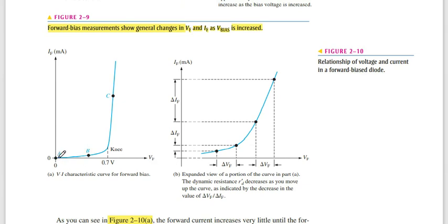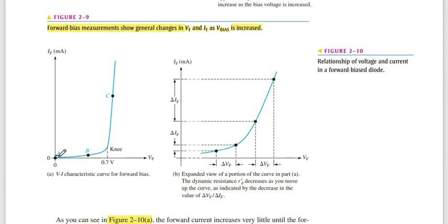First, we increase the voltage gradually from point A to B. No current will flow through the diode in forward bias, only a small amount, nearly equal to 0. You can see it. When we reach 0.7 volt, the current will move very fast from this point to C and beyond.